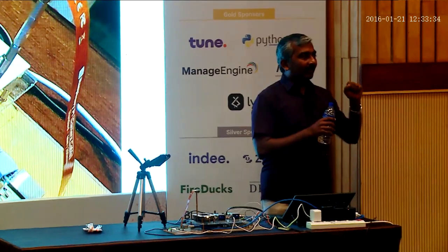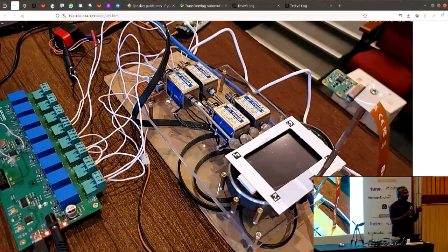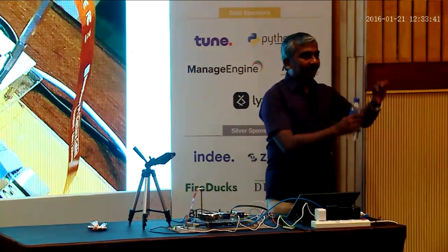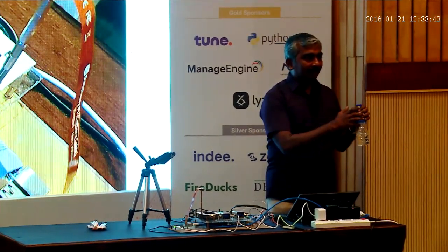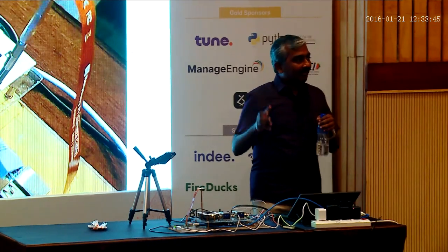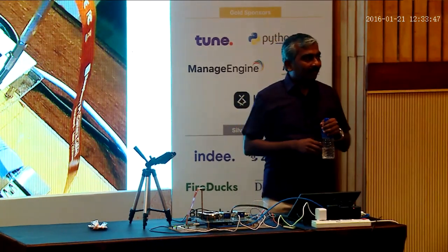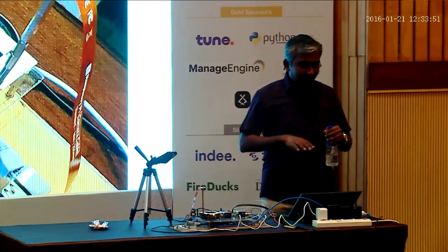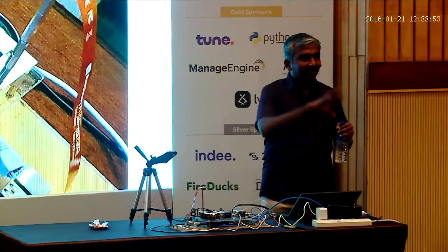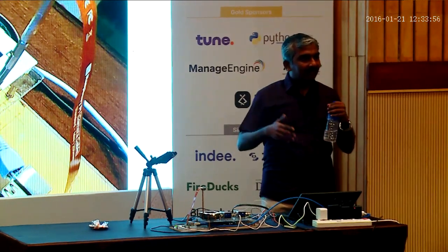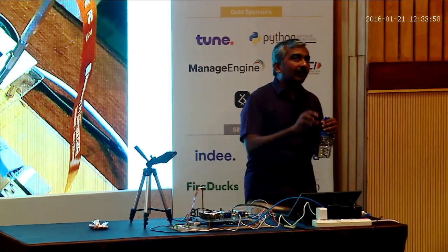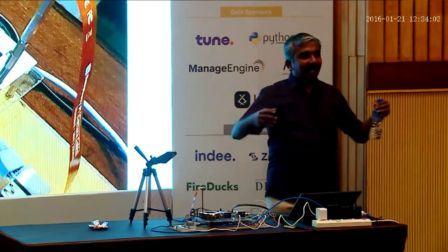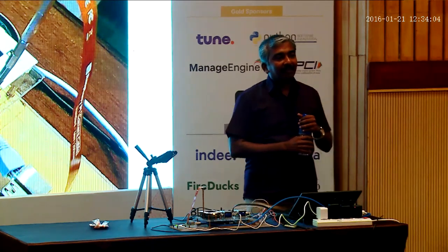Generally, OEMs get these ECUs and put them on a test jig, and then run the test suites on the test jig. Then we have these complex ECUs that have to interact with a bunch of other ECUs and also maybe simulate some of them. So they are also sitting on a test jig, and we have test hardware connected to them that will drive these. So this is for one vehicle design, not necessarily manufactured test of all ECUs.